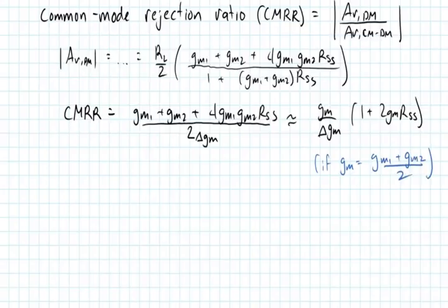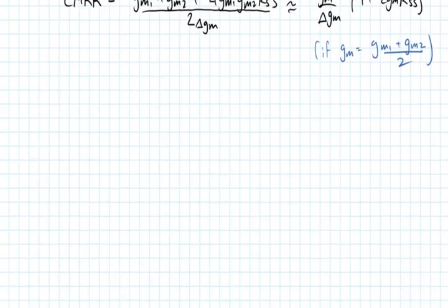Okay. All right. So this is a problem, and as we'll see in biomedical signal acquisition, we really need this common mode rejection ratio to be enormous, higher than you could even think would be reasonable. Actually, it is often desired. So that's a really important thing for us to do as biomedical engineers, is to make sure we know how to design for very large common mode rejection ratio.